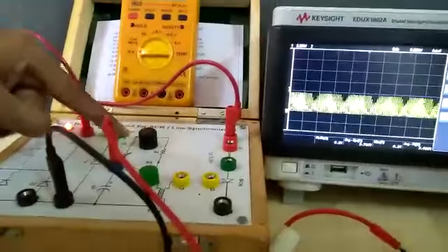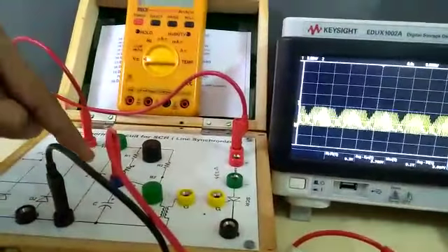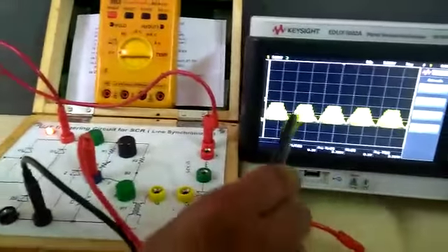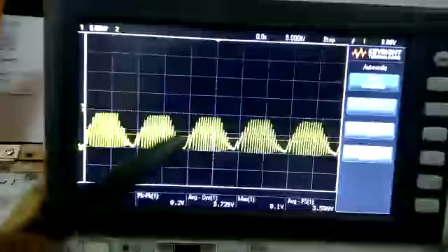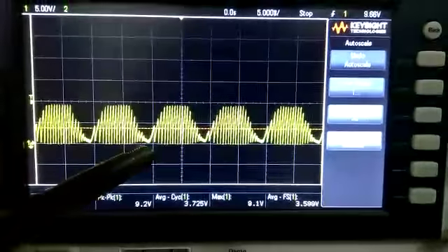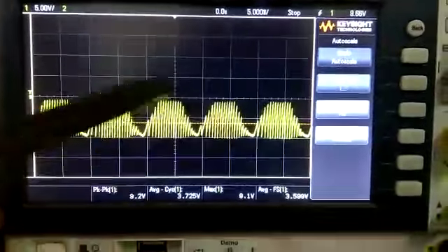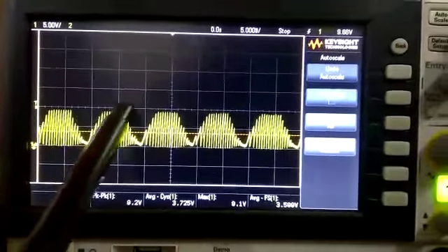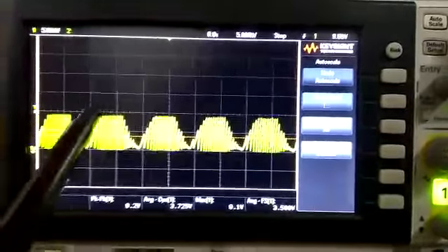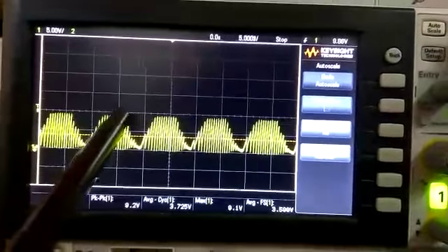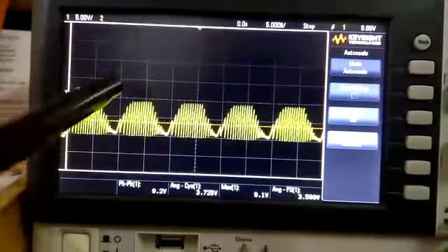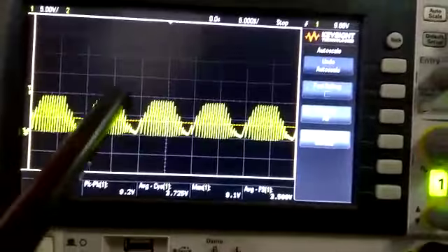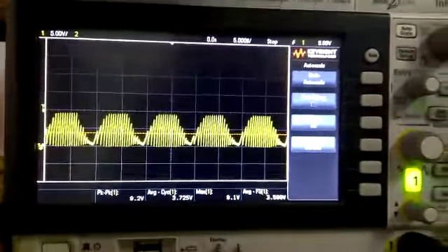By this pot, what I am doing is controlling the magnitude of the current through this capacitor. And what is the indication of this? You see the pattern of this charging and discharging. It is all positive halves. So this is related to your pulsating DC, and you can see one specific level is maintained over here. This is related to the Zener voltage. The Zener is used for voltage regulation, and you can see that regulation here at the top: the curve is not there, it is a flat portion for the charging and discharging of the capacitor.